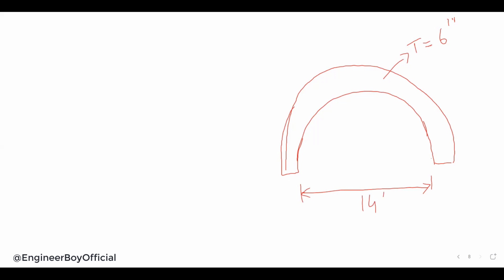And then we have the height of the same dome. I'll take that internal. Let's say the internal height is 7 feet. Okay, what do you see? It means the dome is semicircular because the rise of it is half of its span. It means the span can be the diameter, so we can say that is the radius, which is 7 feet.